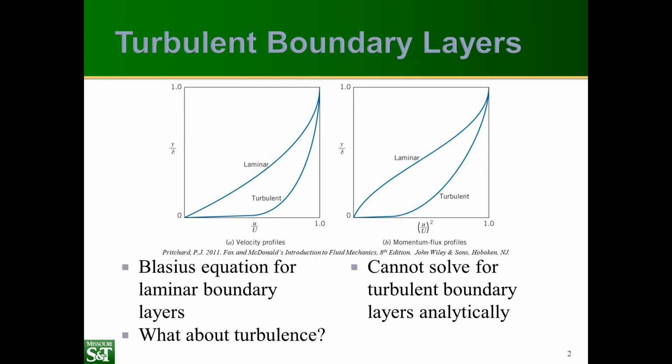And these features are very important. Turbulent boundary layers have more mixing. So the boundary layer is going to grow faster because it's easier to transfer momentum from one location to another. We already talked about larger drag. There can also be increased heat transfer. And the increased inertia of a turbulent boundary layer means that it's harder to slow it down. And it helps turbulent boundary layers resist boundary layer separation better than laminar boundary layers.